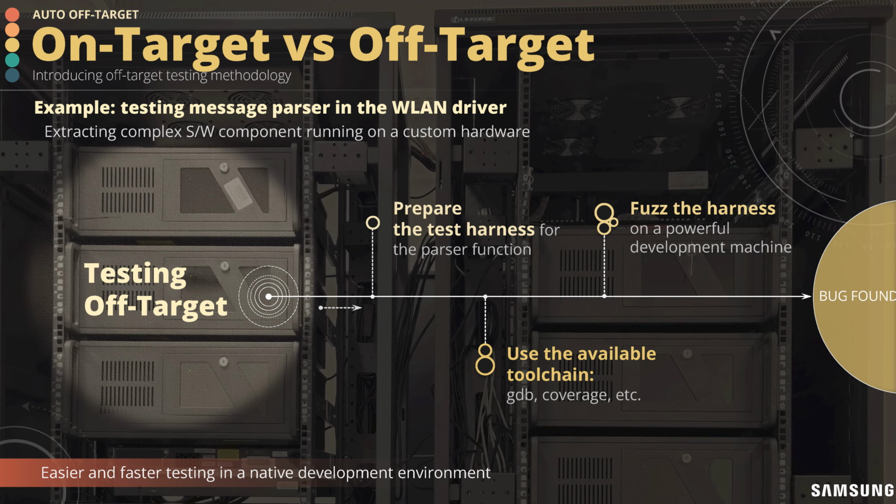So what is off-target testing? You just take this parser functionality, extract it from your full driver code, compile it on your development machine, create the executable, and feed the messages to your parser through this executable.